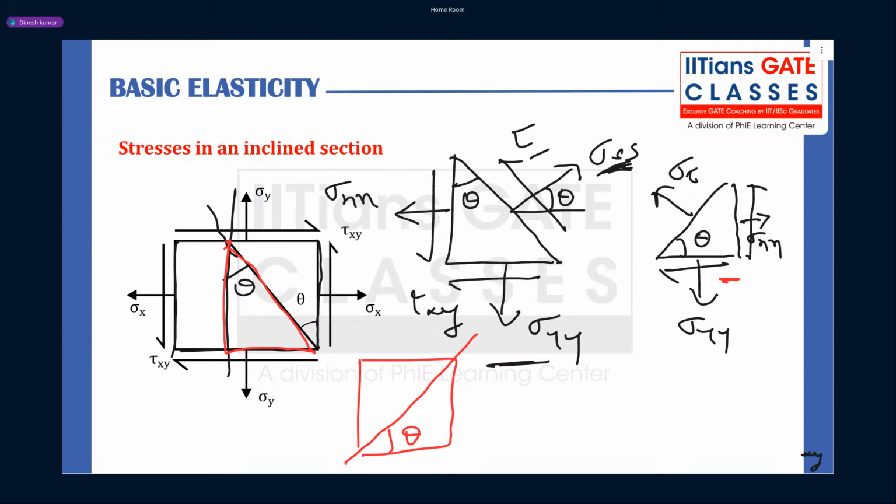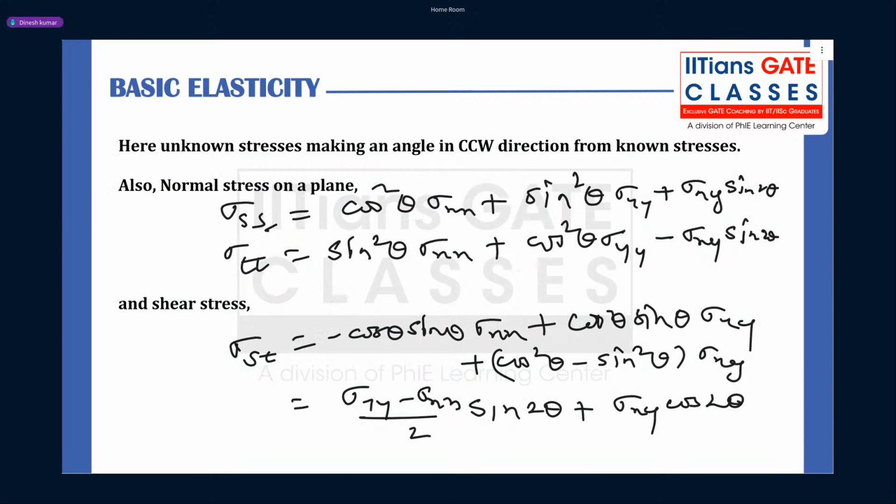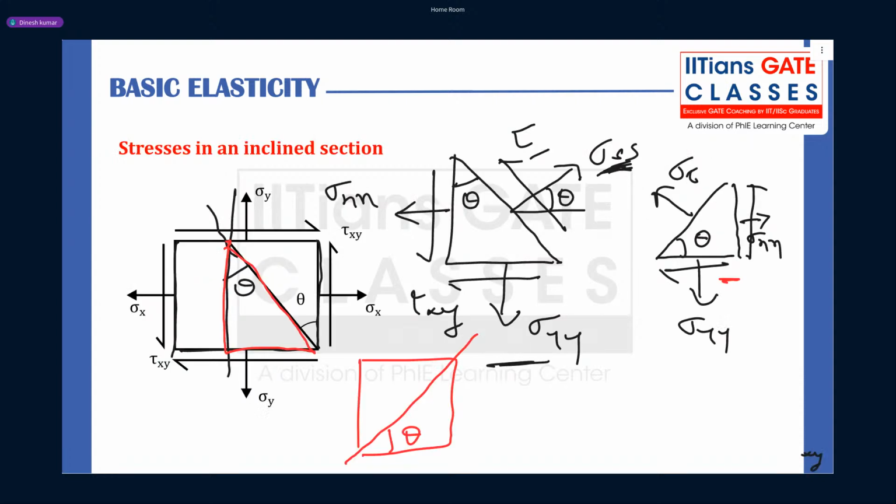Okay. So guys, you have to understand this stress transformation well to solve any question related to SOM in the GATE exam. So these are your stresses. This is the normal stress in the S direction, this is in the T direction, and you understood what sigma TT and sigma SS mean, and this is the shear. The shear will remain the same whether you use this triangular element or this. Now on this, you see the corresponding shear will be acting like this.